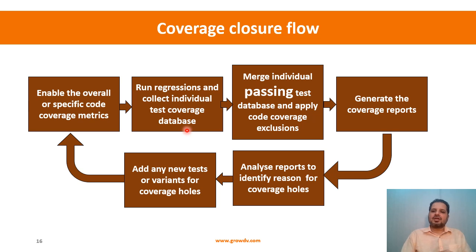So it is like a waveform. You have been, for example, generating a waveform database like an FSDB or a VCD, and opening them up and looking at the waveforms on a per test basis, right? Similar to that, in the test command line, you can enable additional options to the simulator to dump the coverage information. It will dump the coverage information per test. As soon as the test run completes, it would dump a database per test.